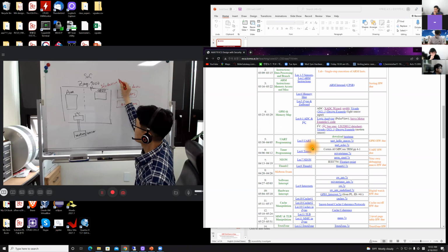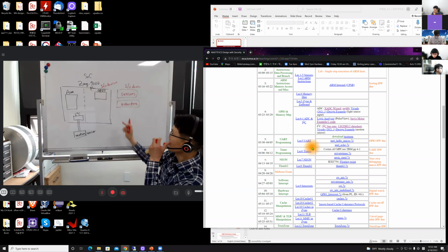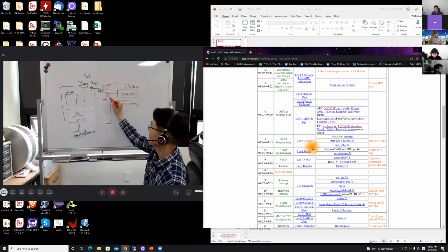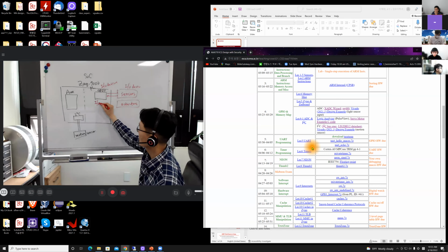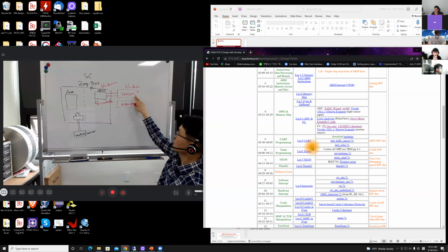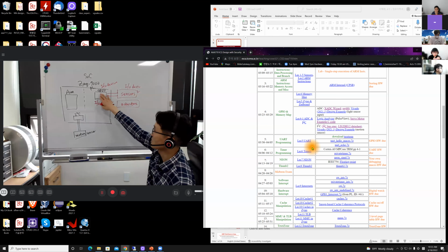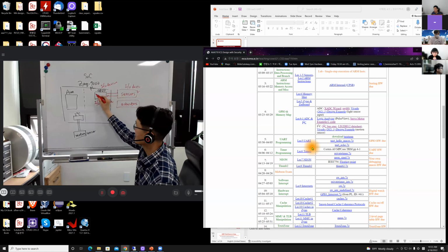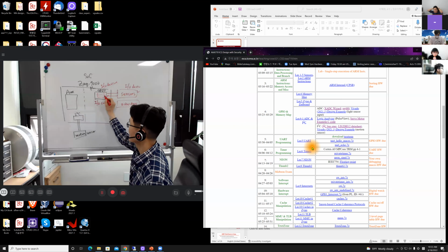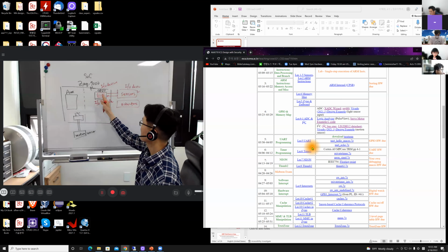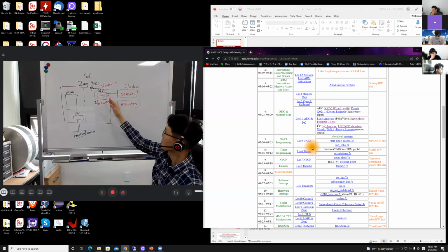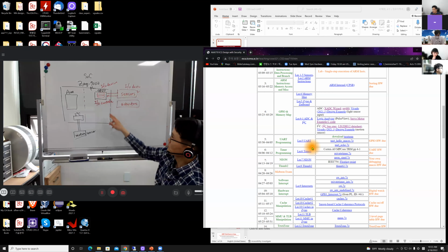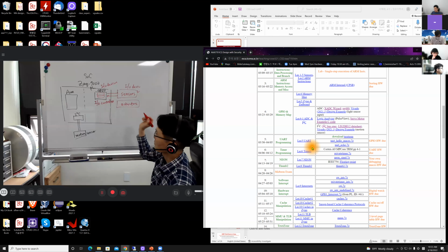It's confusing, right? Inside the chip, GPIO is an I/O device. This I/O device is controlling this I/O device. So in this case, you can think of it as an I/O controller, and that is the actual I/O device. You are controlling these sensors and actuators through GPIO. By using software, you are accessing registers, reading and writing. Then you can turn on some LEDs, and you can take input from a sensor. So you can think of GPIO as an I/O controller.